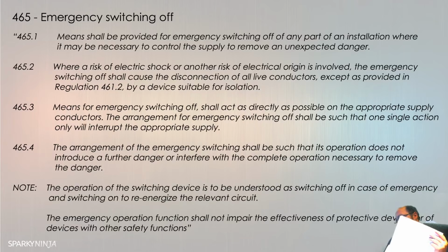And it looks a bit like that. So it's that table there. Now, it's fairly easy to understand this table. We've got device types down the left. This table does go over the page, by the way. This is an example of the bad editing the regulations have done. Device types are on the left. They're British Standard, and then there are columns: isolation, emergency switching, and functional switching, and simply whether or not the regulations consider them to be a suitable